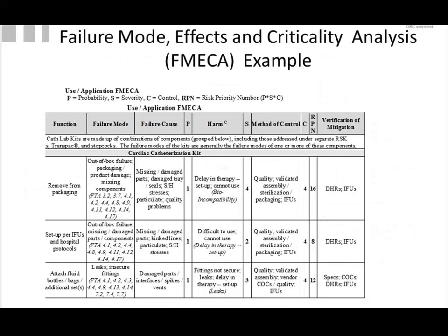You don't have to find the difference between that. As criticality, I list the RPN values, the possibility of occurrence, the severity of occurrence, or probability, and the effectiveness of control to minimize the occurrence, and the ranking, 1 to 5, 1 to 10, whatever. I have those numbers, the FTA numbers, those are actually traceability numbers that tie the failure mode back to an issue on an FTA diagram. There's any number of ways to do this.